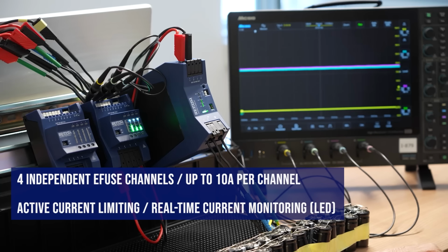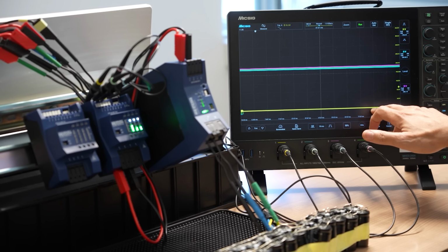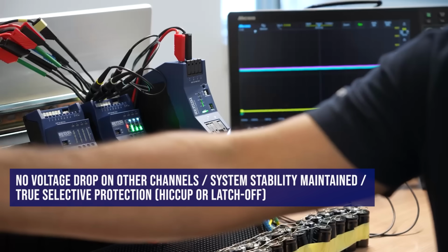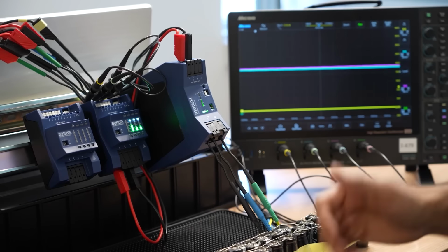Channel 1 gets isolated while the rest are staying intact. So even on our scope we can see channel 1 is 0. Other channels are still at 24 volt. What happens if the short circuit disappears again? So it has auto recovery. For example, we have different modes here. Now it's in recovery hiccup mode. So then we put back the load, it comes back again normally, and the whole system runs smoothly again.